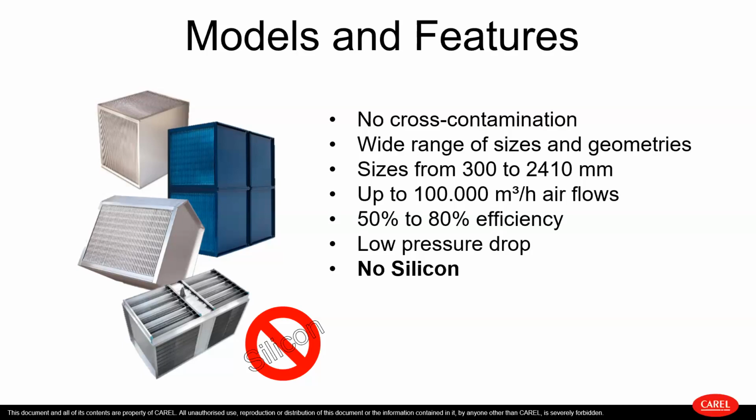Talking about efficiency, with the plate heat exchanger, you can have a temperature efficiency from 50% up to 80%. In this specific application, a really common efficiency is more or less roughly 55–60%. Why not 80? Why not 50?